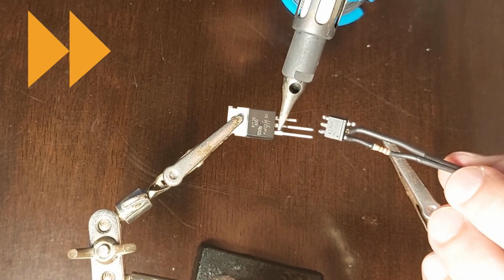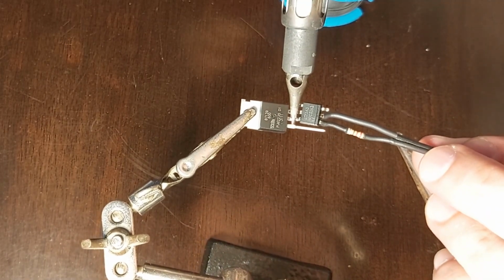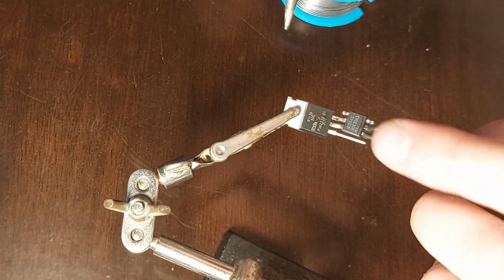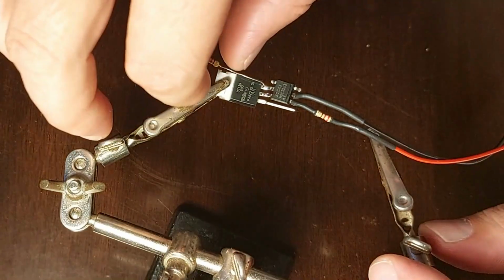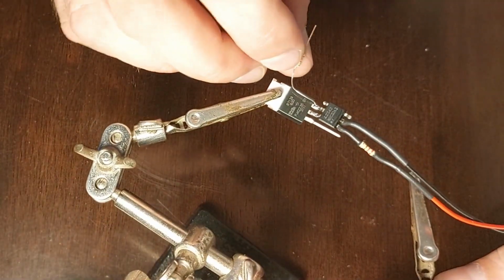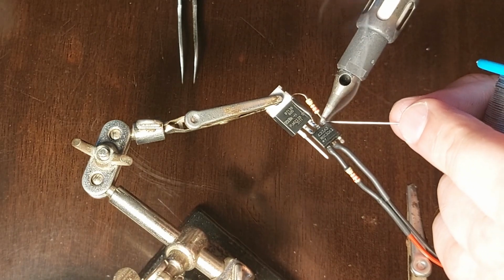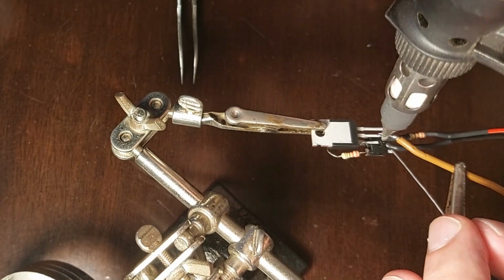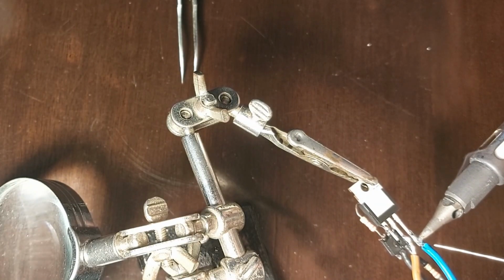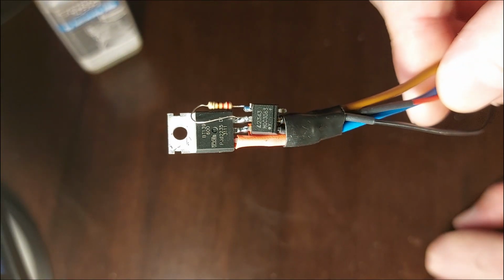Such power components are made to dissipate heat, so I had to heat it up really hard to make a proper joint. After a moment of hesitation, I finally decided to continue, as I was curious what was going to happen. So I added a limiting resistor between the triac gate and the second terminal of the opto-triac, soldered extension wires to the triac terminals, and after adding a few heat shrinking tubes here and there, the module was ready.